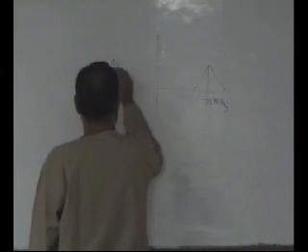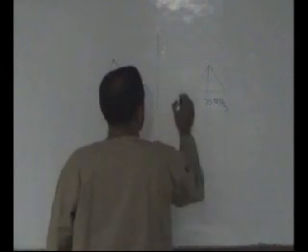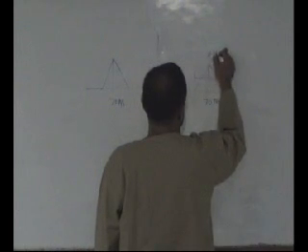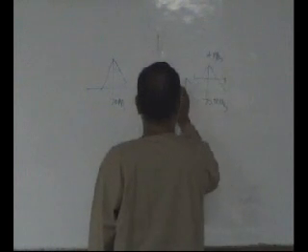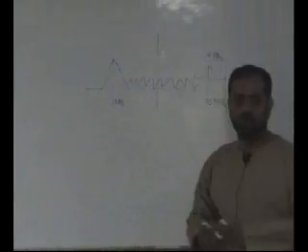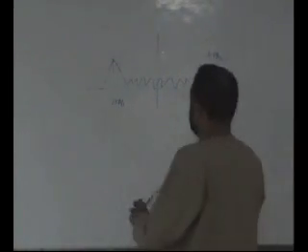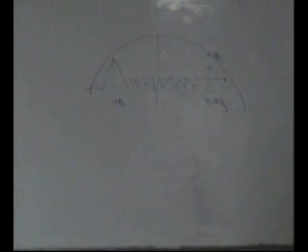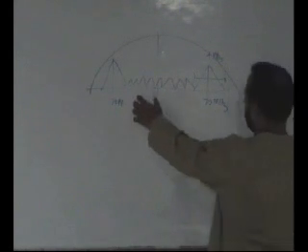The bandwidth is, for example, 4 megahertz, but this part of the spectrum is not clean. So you have passed it through an analog low pass filter, something like this, which has given you the entire spectrum from minus 72 to 72 megahertz, but part of the spectrum is not clean.